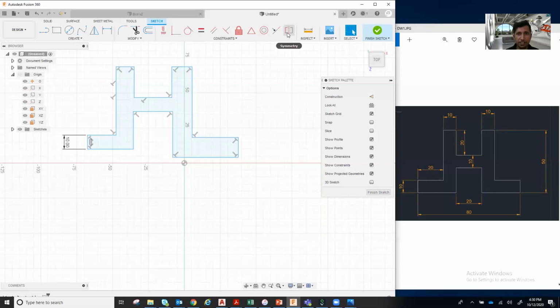So you can use these geometrical constraints to ensure the drawing, whatever you have created, is as per the requirement. Now, for example, I select this collinear constraint. This line and this line should be collinear. Now you can notice these two are in the same parallel plane. And I select these two collinear. Same thing, I select these two as collinear, right?